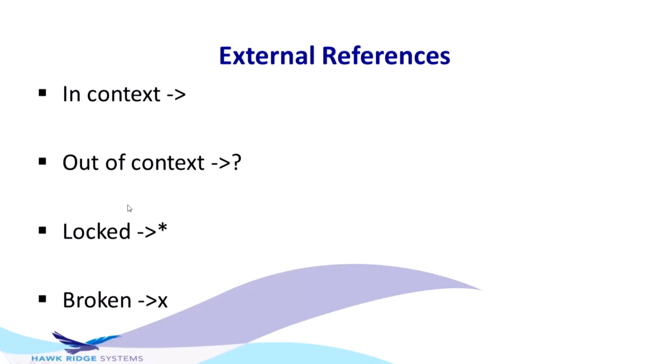There's also an ability to lock your reference. This will allow you to not add any more. It's kind of like suppressing and unsuppressing your reference. Say, for example, you want to test something out, but you don't want to remove the reference. You're able to lock it. And then also there's a broken reference where you say, you know what, I'm going to use this in another assembly. I don't want to automatically update it anymore. You can just quickly break it. So let's do the last two.